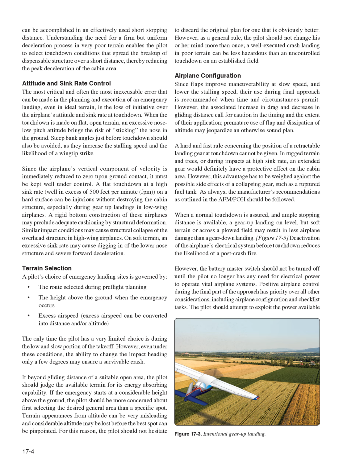Airplane configuration. Since flaps improve maneuverability at slow speed, and lower the stalling speed, their use during final approach is recommended when time and circumstances permit. However, the associated increase in drag and decrease in gliding distance call for caution in the timing and the extent of their application. Premature use of flap and dissipation of altitude may jeopardize an otherwise sound plan.